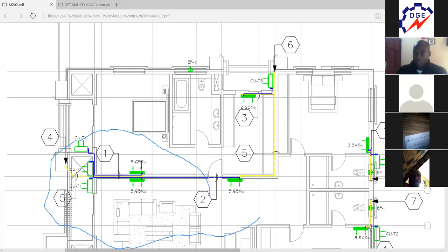That's why you have them in split, simple, miniature sizes. You have your specific unit to cover this space, and you have a separate unit to cover this space. Because what we have eventually is an airflow coming in this direction. When it bounces back off this wall, when this space is fully composed of cool air, it will blow in this direction. Then the second one, from this direction, will blow in this direction over time. So you will have a slight dead point at the entrance of the space.